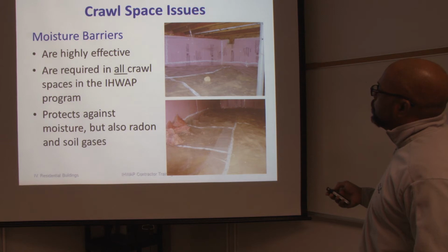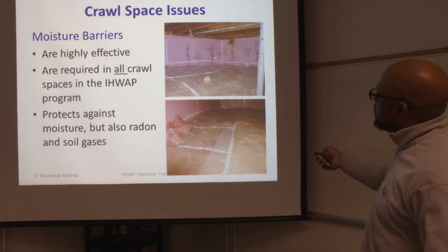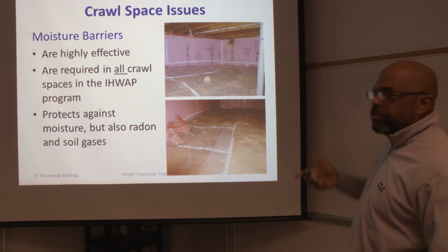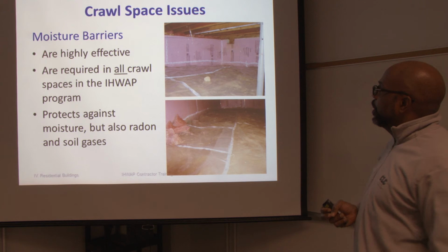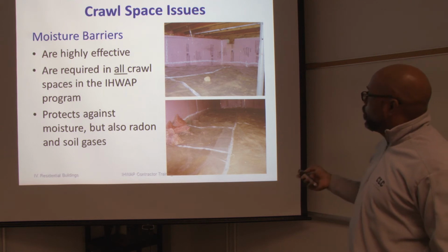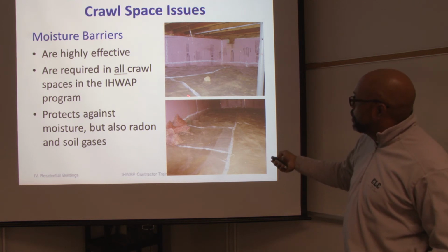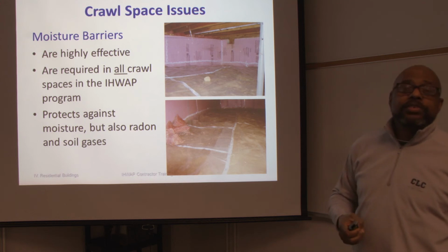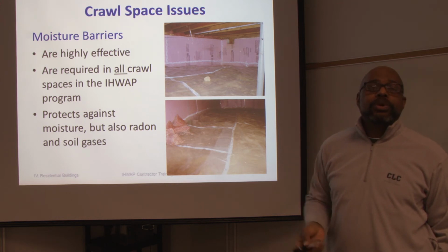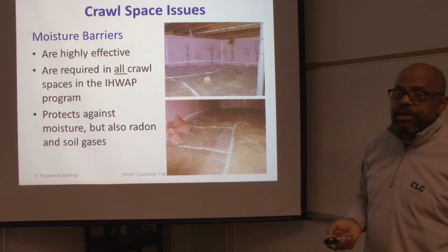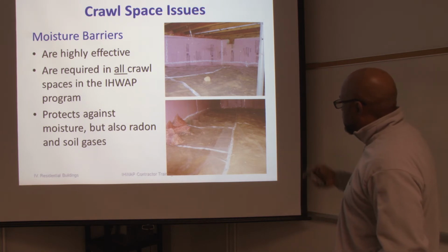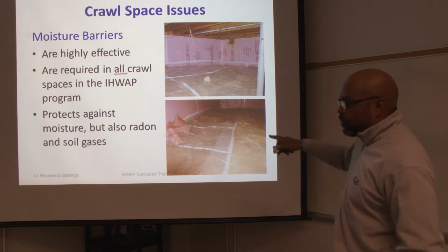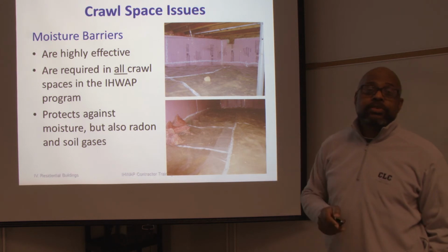Now to get into crawl spaces, there are some ways we'll do it. We will seal the walls up with insulation. We put some type of visqueen or some type of sheeting like plastic over the crawl space floor. We will seal it up to make sure there's no moisture that can leak through, just through vapors from the ground. So this will keep the basement from having issues with moisture building up in the rocks or the dirt, or sometimes even concrete.